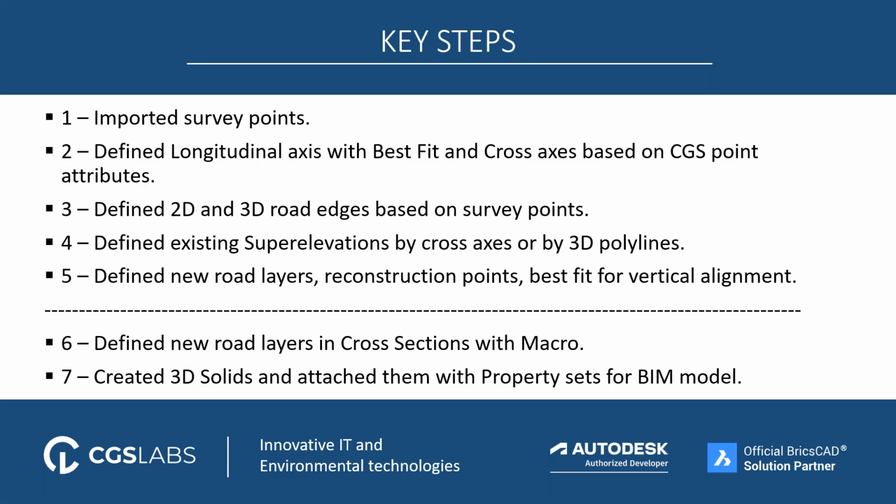So to recap, I would like to go through the steps that I showed you today. First things first, we imported the survey points that represent our existing road. We defined axes based on attributes that were on these points, with the best fit command and the cross axis on the CGS points.